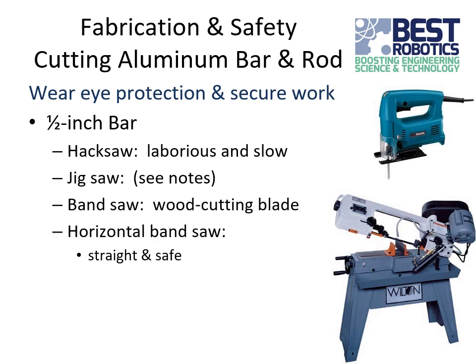I've done it this way before. I've cut it with the hacksaw, and it works. Just make sure you have a good blade for it, and they make metal cutting blades for hacksaws. You can use a jigsaw too. They make a metal cutting blade for that as well.